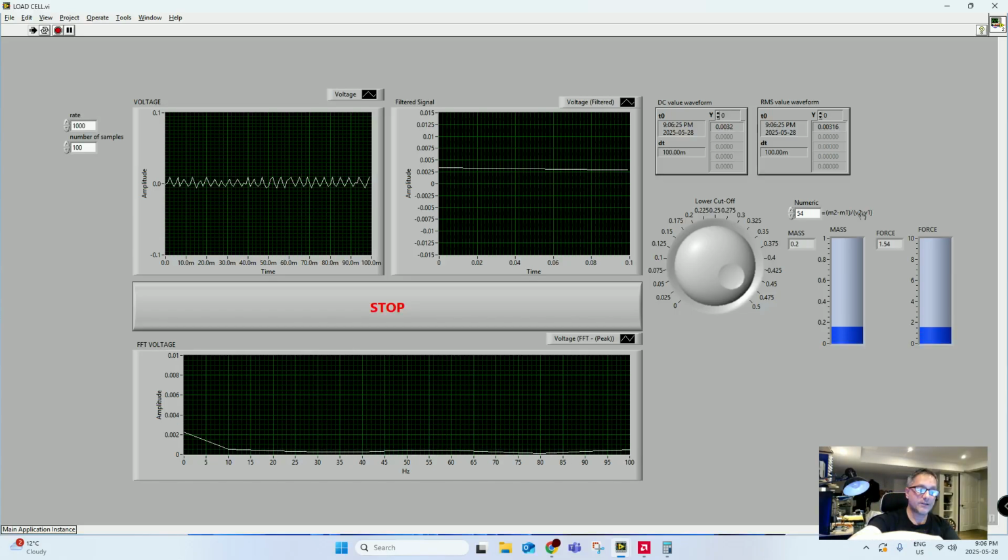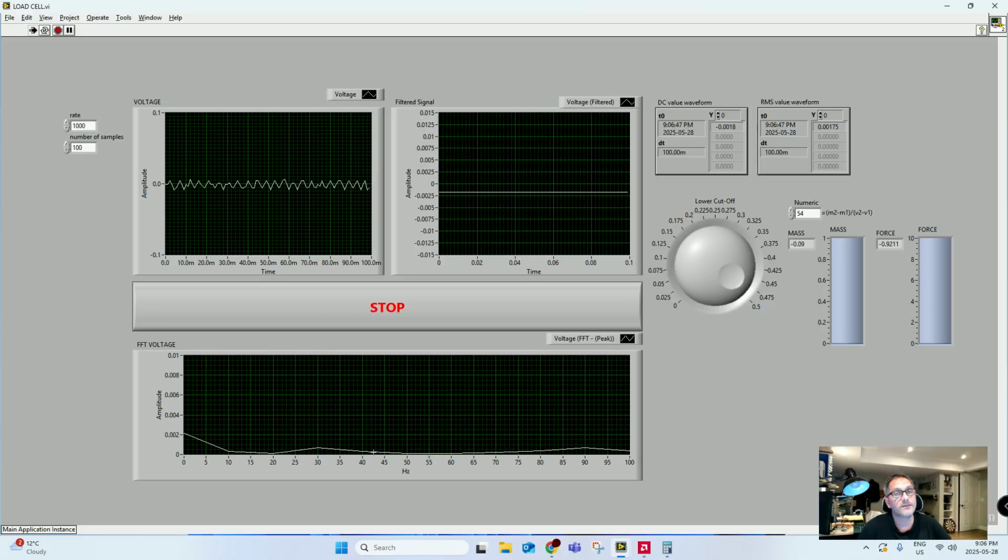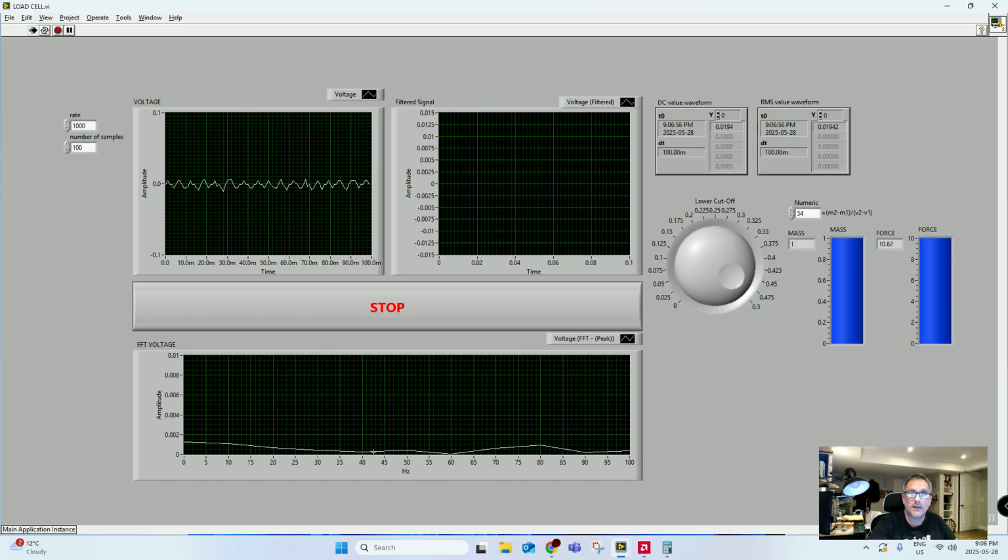Another interesting part of this schematic performed with LabVIEW is that we have an FFT. In reality, the FFT is not usable when you calculate the static load. The FFT allows you to capture the signal component when you have a load or signal versus time, so a variation, for example, like that one, like this.